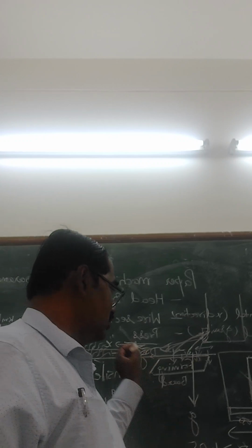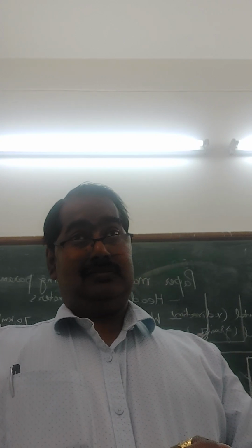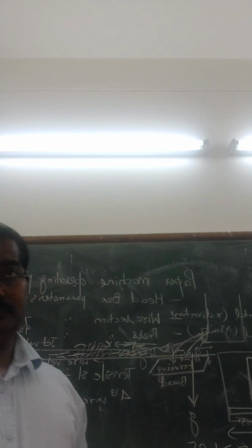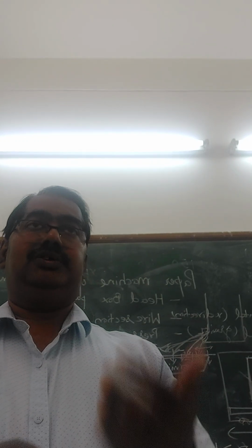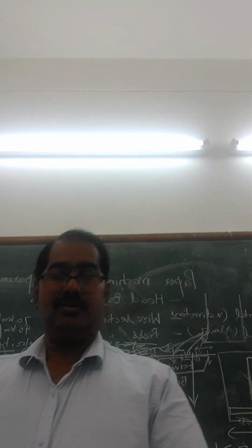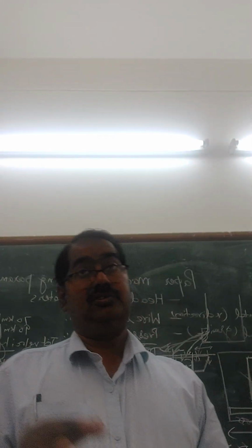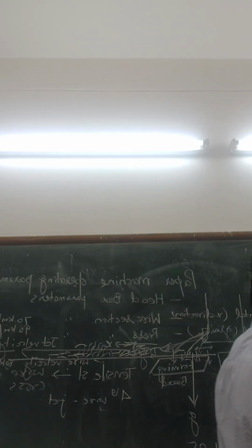So this is the way to control the properties of paper based on the operating parameters of the headbox. We can either increase or decrease the opening of the headbox to control the jet velocity so that the jet to wire ratio can be controlled. And by controlling this ratio, you can control the different strength parameters. Second one is the formation again.